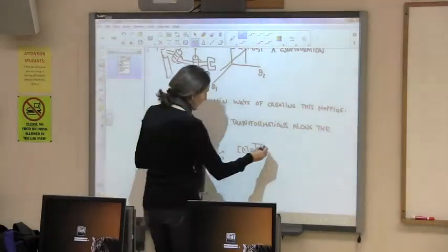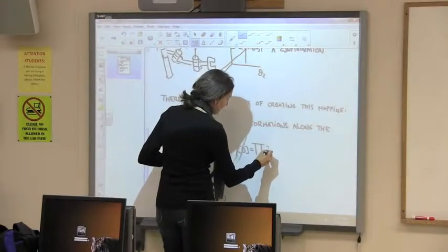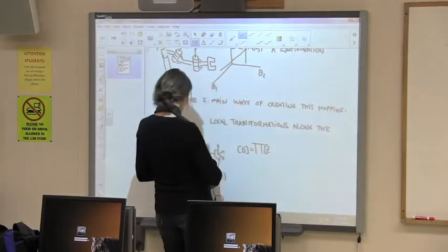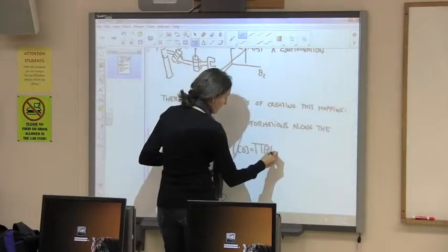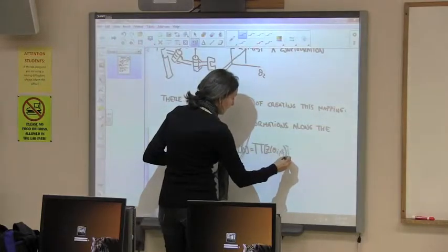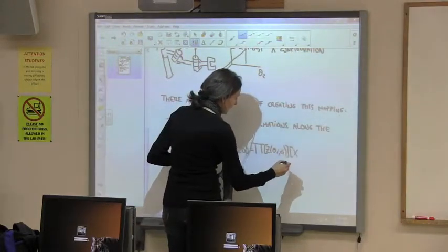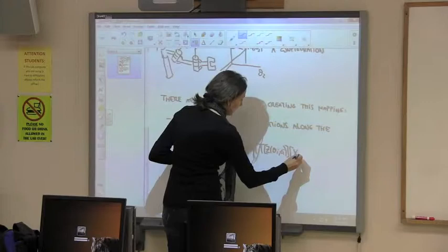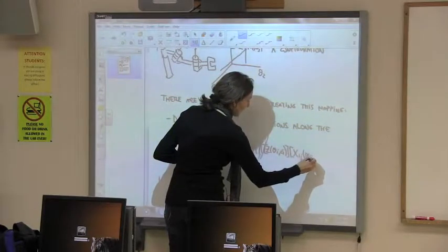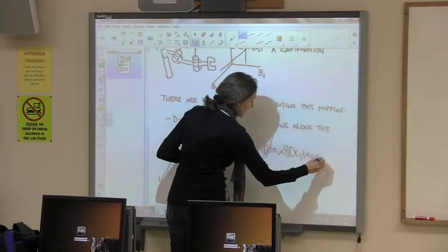So it's basically the product of some Z transformations, Z of theta i, d i, times X i j of alpha i j, a i j.